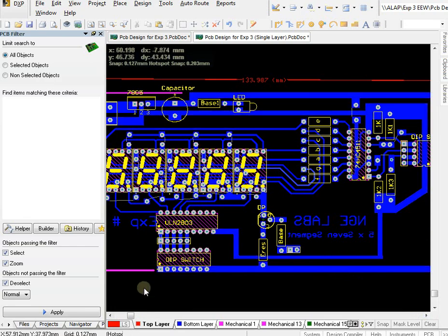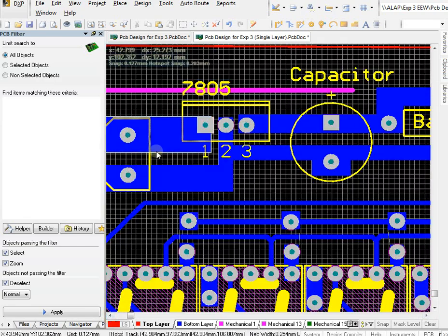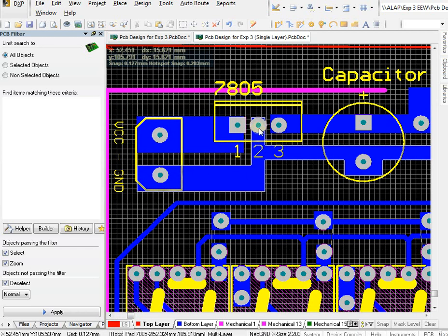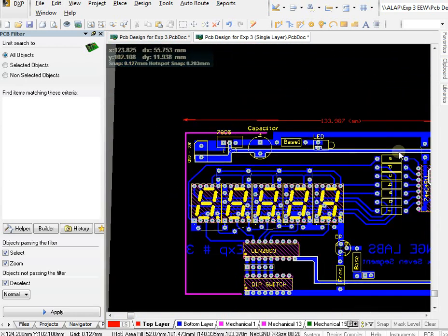I have tried to maintain from the VCC. You can see from VCC to the regulator, it's going to be huge current, its fill area large. From the ground to this regulator ground, its thickness is more. Then from this ground, you can see this ground is traveling.